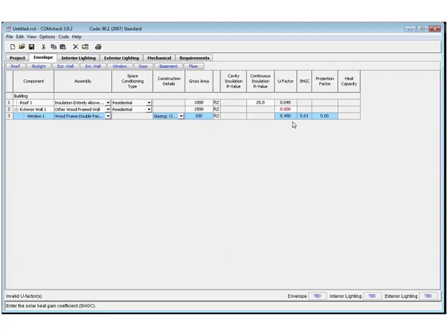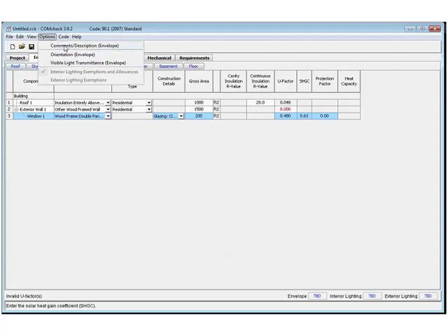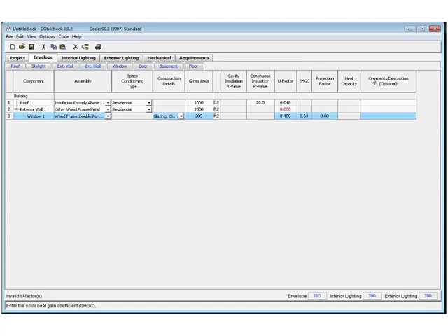And it should also be noted here, when you are selecting defaults, really hard during plan review, if they're trying to go find on the specs to verify that those U factors are specified on the specs of the plans, and then when they go out in the field, and let's say you still meet compliance by using defaults, let's just say that. How is one to know unless you give them a little bit more information here? So how can we do that? We go back up to options. Let's click on that comments description. And now here we have that column that I talked about earlier in preferences, if you wanted to have it there every time, that I could add in that I used default values.